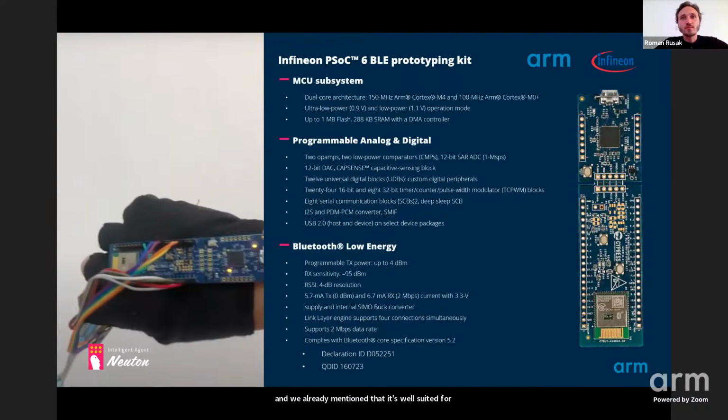Also, the dual core architecture allows you to efficiently use various components of your system. For example, porting the ML model and all pre-processing algorithms to the Cortex-M0 and running inference there, thus leaving the Cortex-M4 for the Bluetooth stack, motor control of the electrical toothbrush, and business logic.